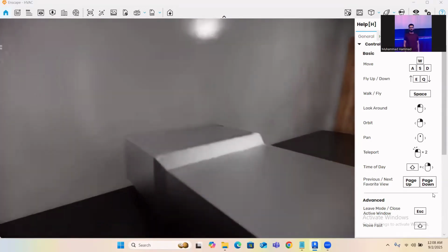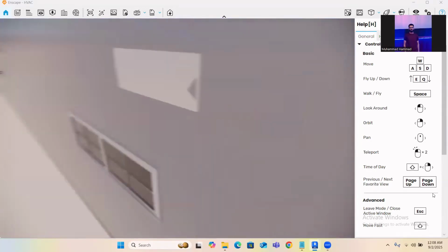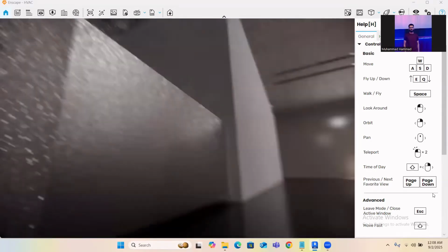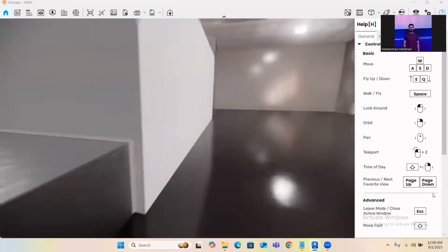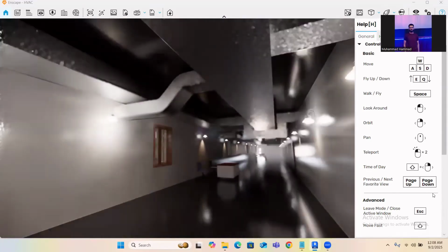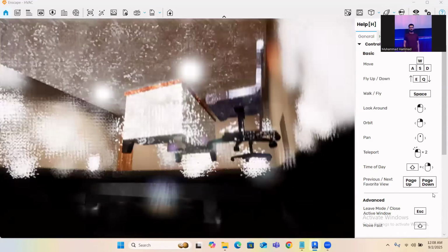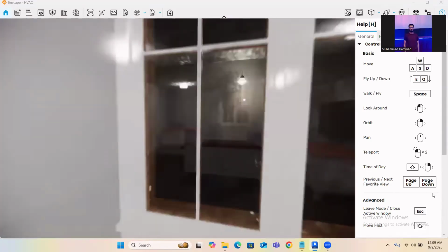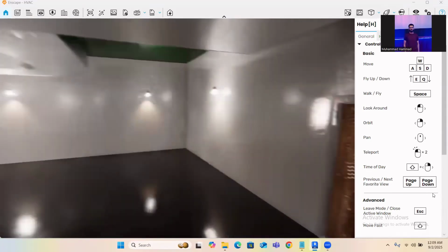And here is the fresh air supply to the air handling unit, which you can see is at the lower part where it gets the fresh air, and then the return air. This mixed air passing through the fan and the cooling coil is supplied in these areas. So this is a three-story building. Each floor has its own ductwork and diffusers.